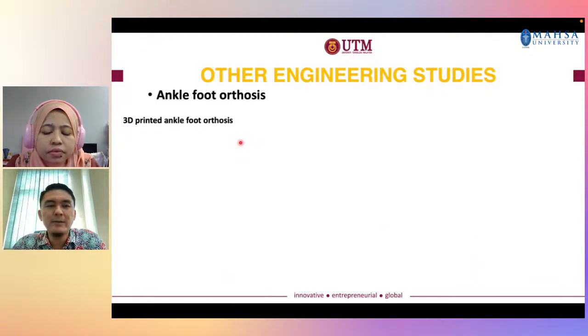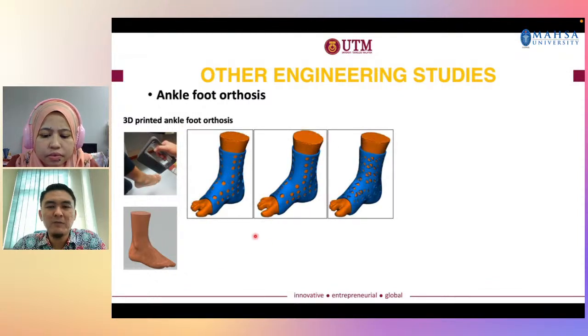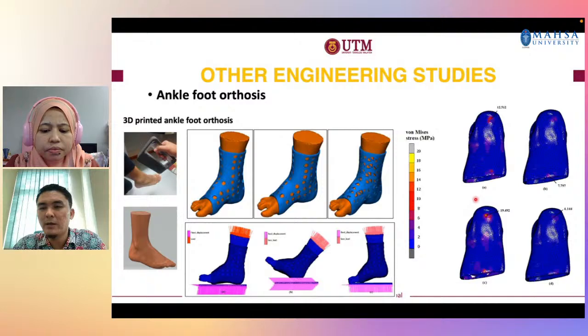And then the other study on the ankle foot orthosis, same method where we scan the foot using a 3D scanner, and we develop a series of orthosis designs having different designs of holes, and then we do some finite element analysis, and then we simulate the stand condition, the heel strike condition, and also the toe off condition. And then we found that three of them are okay for